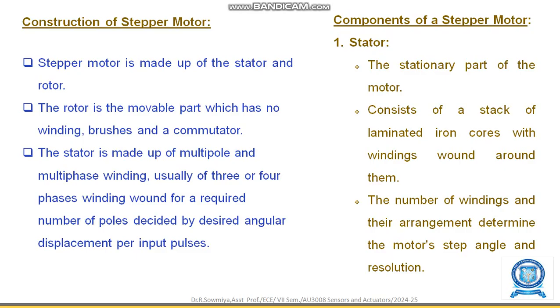The components. Stator is a stationary part of the motor. It consists of a stack of laminated iron core with the winding wound around them. The number of windings and their arrangements determine the motor step angle and the resolution.